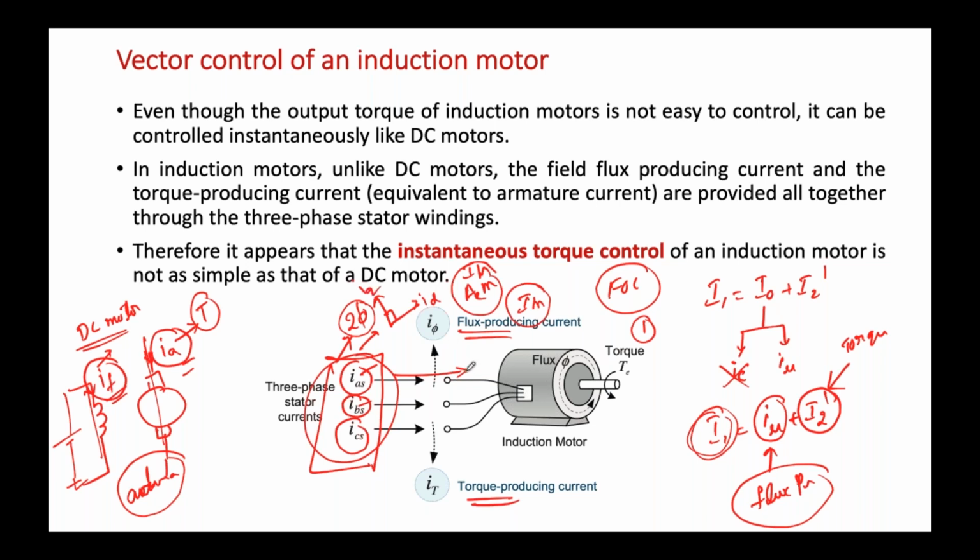So finally, in case of the FOC method, to get clarity among these three-phase currents, how much field flux we need to control and how much torque producing current we need to supply to the machine, the first step is they will adopt the transformation technique. After applying the transformation technique, what benefit will you get as a controller? You will get complete information. Three-phase currents will be converted to two-phase currents, and this two-phase current space displacement angle is 90 degrees.